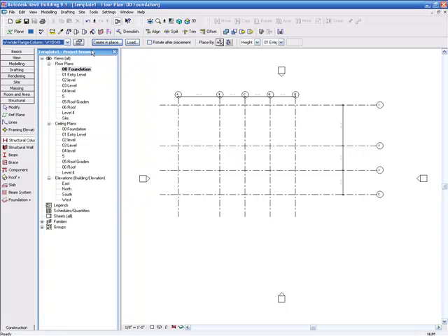I'm going to go to the options bar, which is right in here. Select height. Okay. And we're going to say go to the roof. Go to the roof garden. Okay, so in the event that something changes height-wise, these columns are going to know to go exactly to the roof no matter what.